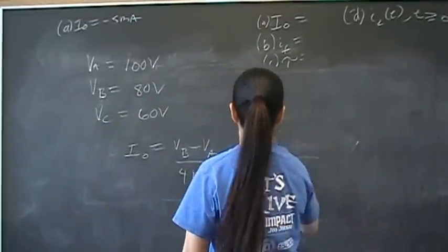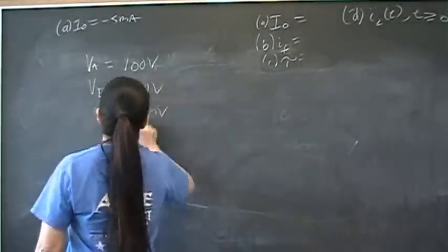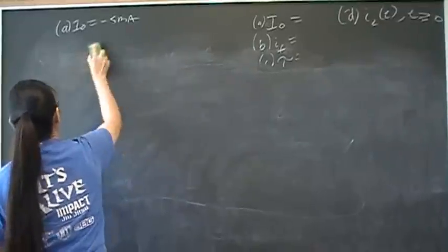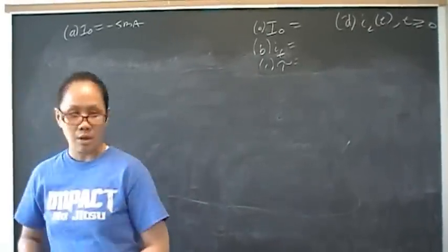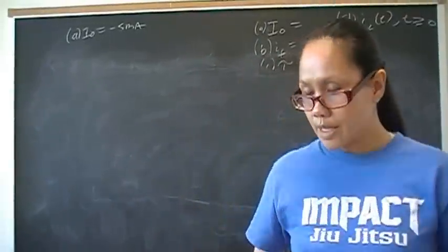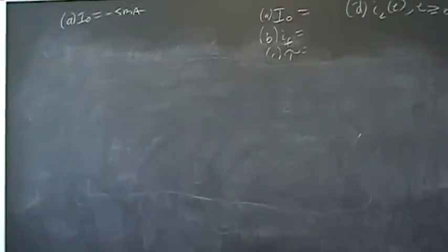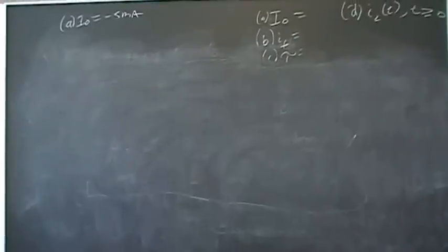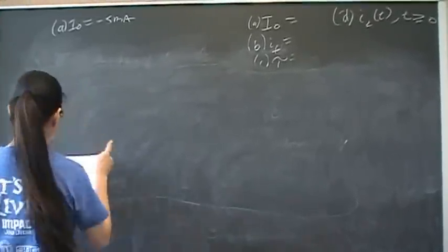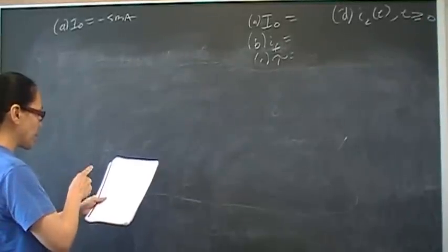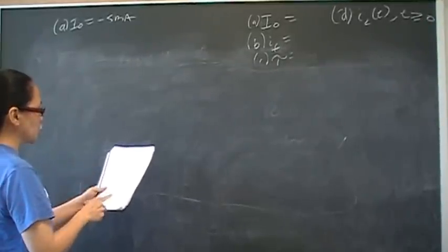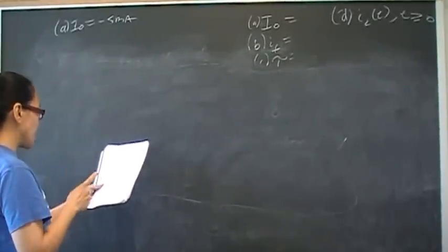So we need to find the final current through the inductor. So let's draw the final current. Now that switch closes, shorting the circuit entirely from the 150 volt independent voltage source, the 5K, the 20K, and the 4K.